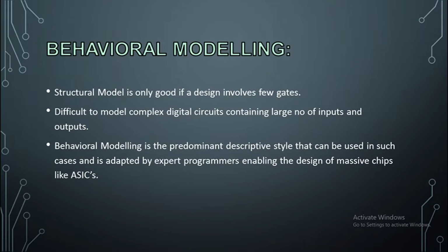But as the number of gates or inputs increases, the structural model becomes very difficult to handle, because you have to declare as many wire variables as there are gate outputs. The number of variables increases, and it becomes difficult to connect them together properly to create a proper schematic. That's why structural modeling becomes very difficult for creating complex digital circuits.